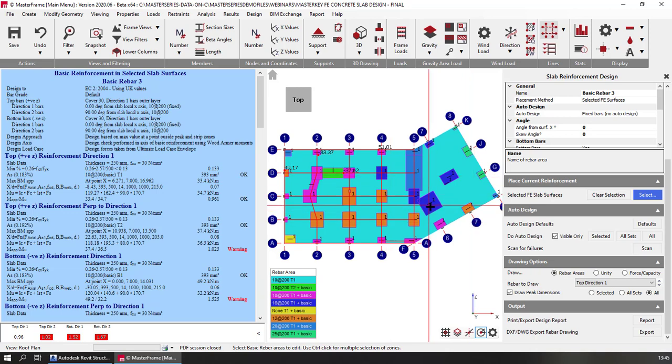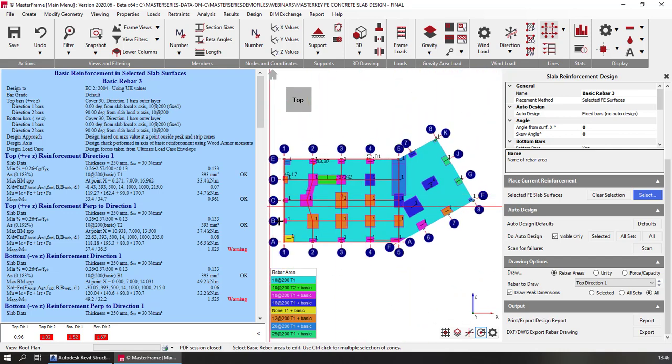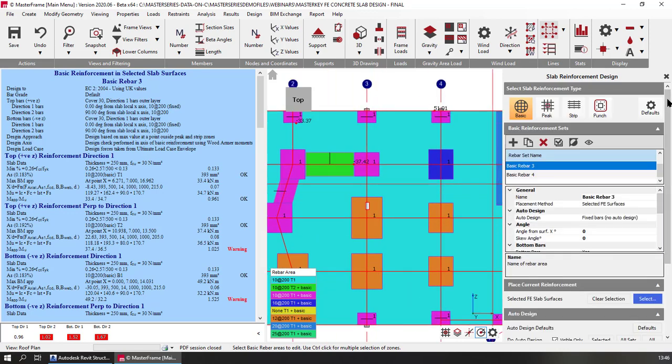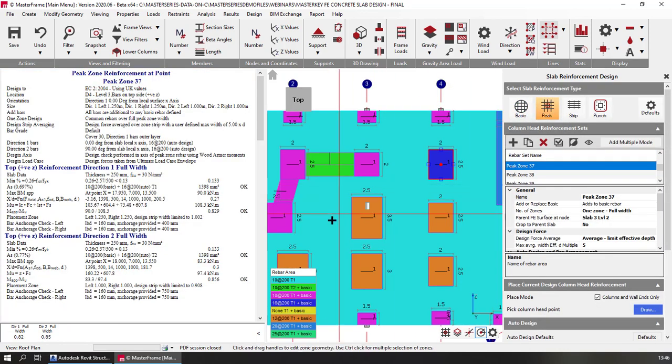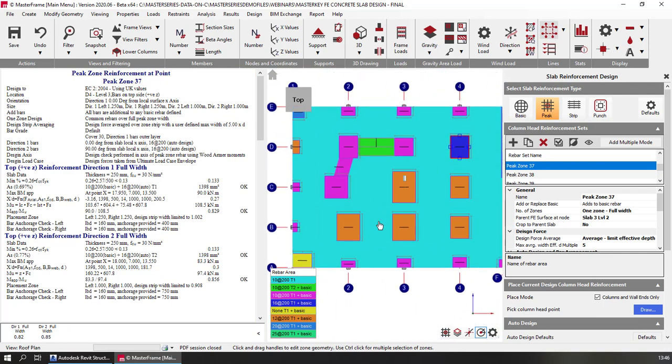And bear in mind that the rebar here is going into different to here, so we will need a lapping bar between the two sets. And we can take that and export it. And as you saw earlier, if we're in peak modes, we can take these and we can rationalize their sizes. We can rationalize their required rebar to make everybody's life a lot easier on site.